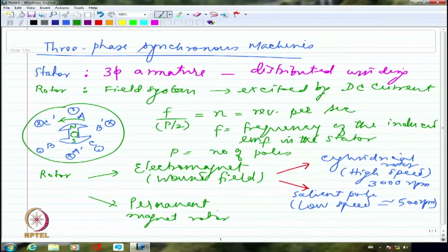So this is going to essentially allow the machine to have its own excitation with the help of permanent magnet. So on the whole, the machine will have a revolving magnetic field physically created because of the rotor magnets and electrically created because of the stator induced EMF eventually, which will cause induced current. That is also a three-phase current that will definitely create a revolving magnetic field. So ultimately both these fields align themselves with each other.